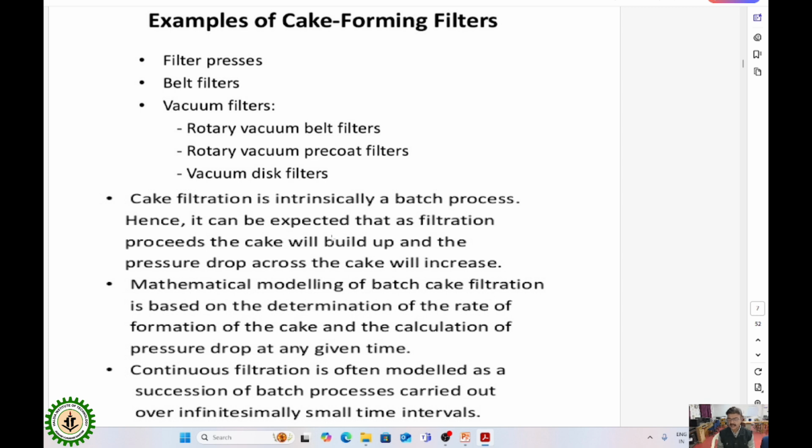These are generally operated in a batch process because with some time of filtration, it will get exhausted. So we have to clean it, and then after cleaning the device, it will be taken online again. So a time gap is required in between. So it cannot be used in a continuous process successfully.